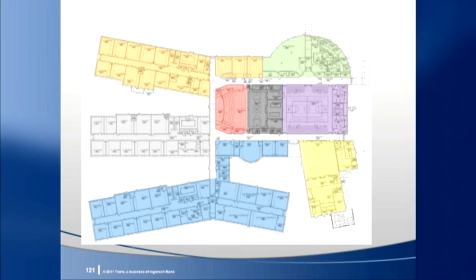to. For example, in this high school, a dedicated outdoor air handling unit might be located to serve a wing of a classroom, such as the middle wing on the left-hand side colored gray. The water-to-water heat pump might be installed in a small closet in the wing to minimize the cost of piping and ductwork. We packed a lot into this broadcast, but hopefully you can use the 4 primary goals that we